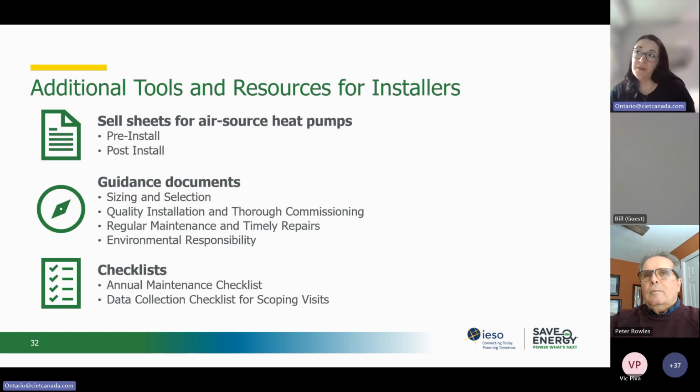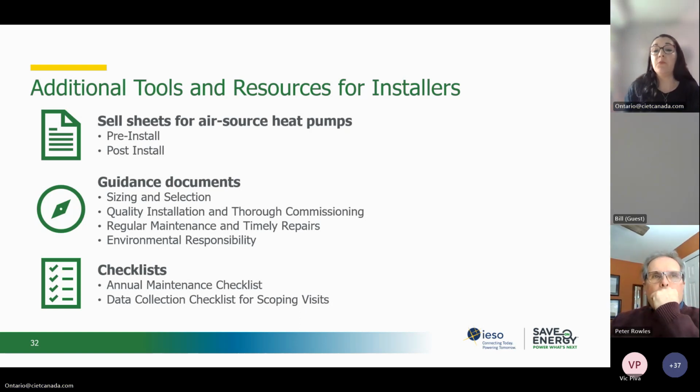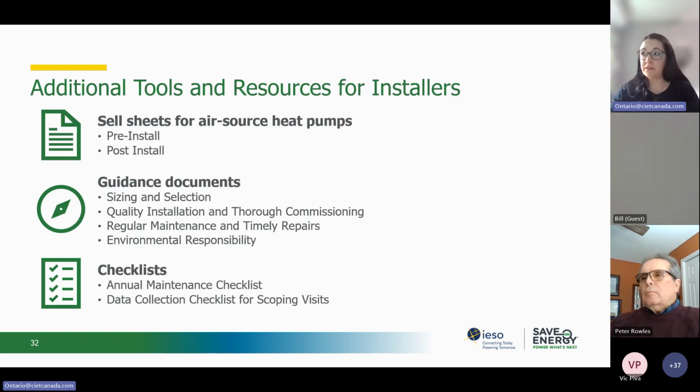What is considered cold climate? I don't have a direct answer to that question, but I think a lot of the standard heat pumps would just stop operating once it got to be about -5 degrees Celsius outside. Basically, they would cut out. They weren't able to keep up anymore because they weren't capable of dealing with that cold of outdoor air as a supply. And like we've reiterated, the cold climate heat pump has to maintain a specific level of performance down to -15 degrees Celsius.